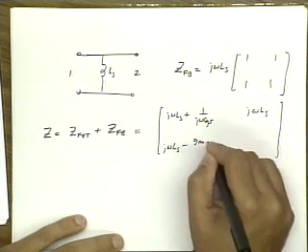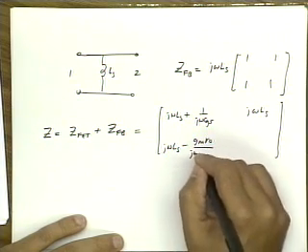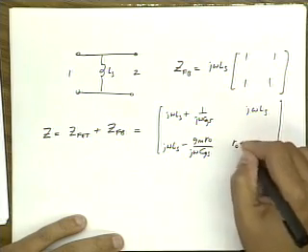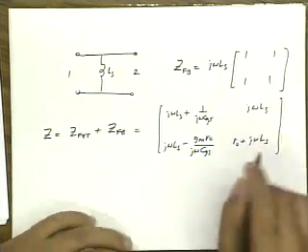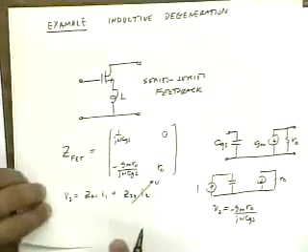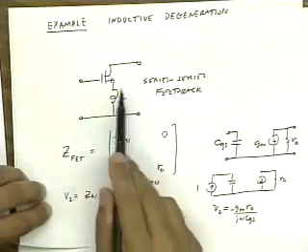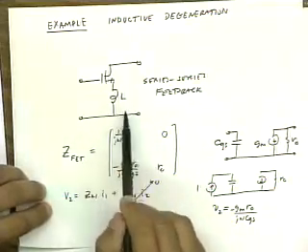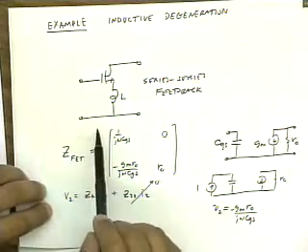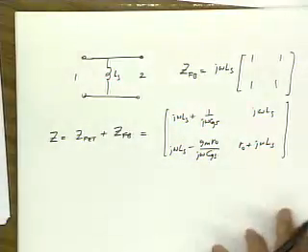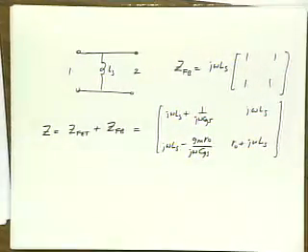And this again is something that you should, whenever you see a circuit that doesn't have feedback to begin with, and you do something to it that introduces feedback, you should worry about stability, especially at high frequencies. So just adding this element here clearly introduces a Z12 factor, because now part of the output voltage appears at the input. The output current generates an input voltage. Okay? So this is the overall Z matrix of the system.